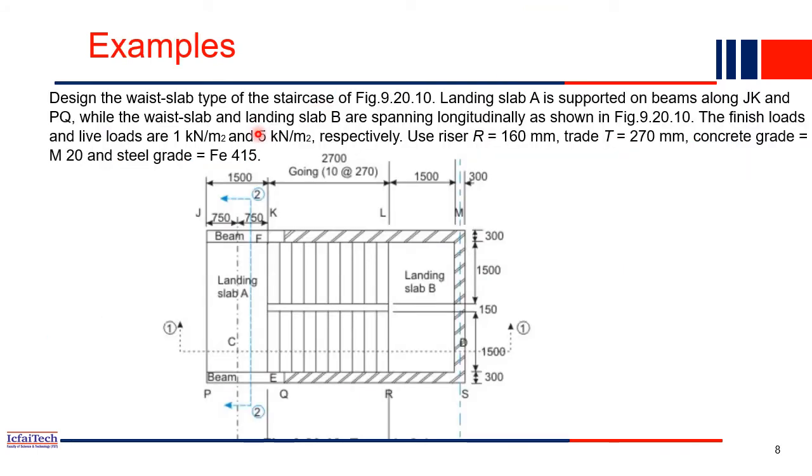Now let's see one example of how to design a real life staircase. Okay, so now we understand staircase can be divided into beams and columns and slabs as well. So the main riser portion, or the main bottom portion, we can design as a beam design, and the landing portion we can design as a slab design, and obviously on all the sides we have the columns also. So let's see an example here.